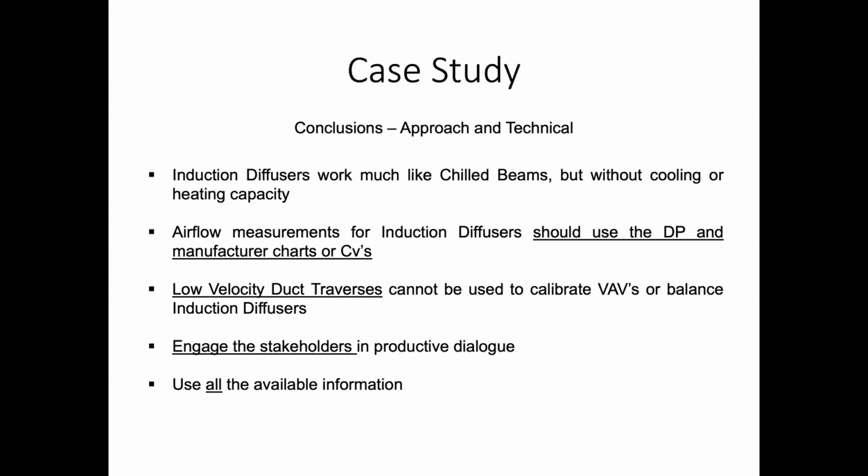Yeah, so the discharge air temperature in the room is difficult to measure because you can't get a place near the diffuser where it's really accurate. There's so much air movement there.